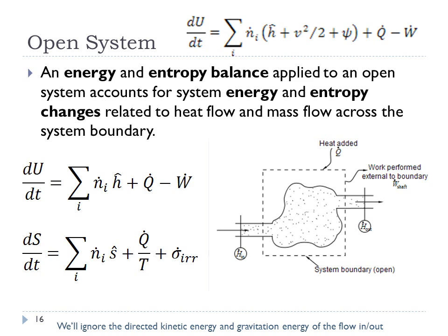So we now have these sigma terms, where sigma is the summation of the number of moles of species i times the molar enthalpy of species i. That's one of the terms that shows up, and it's the one showing up in the first law of thermodynamics.